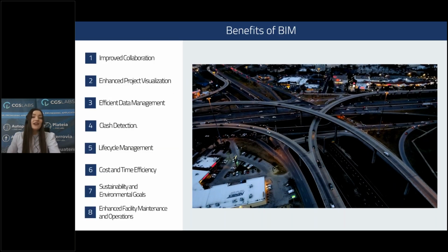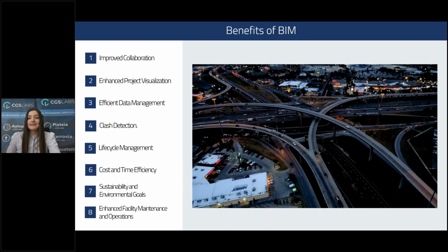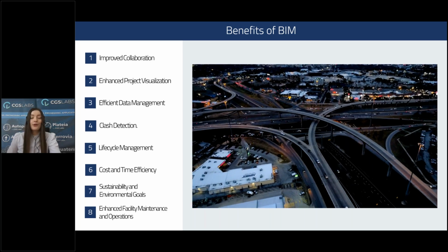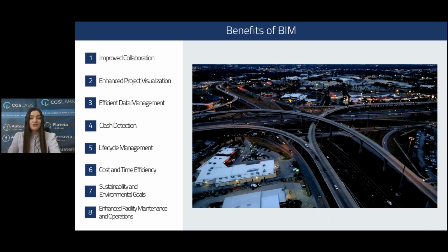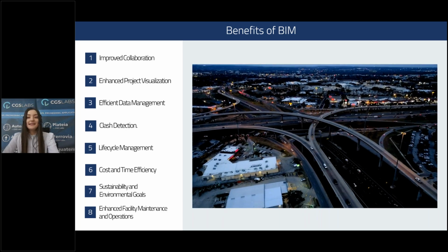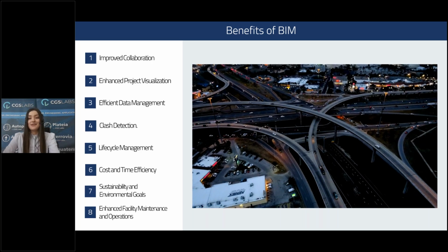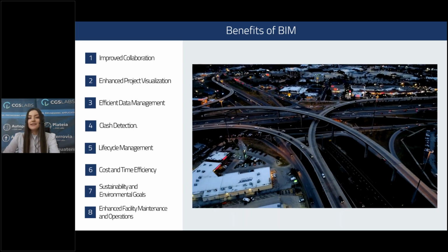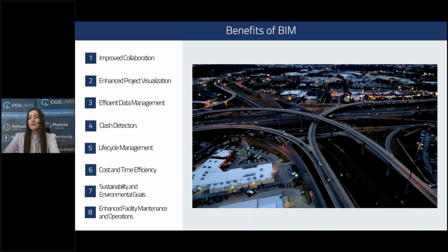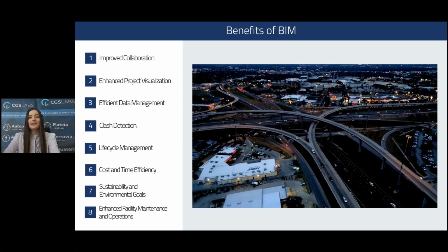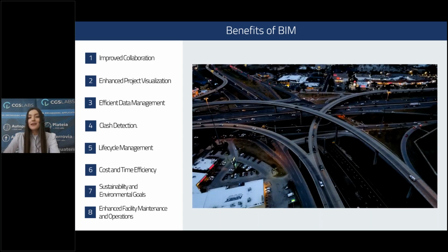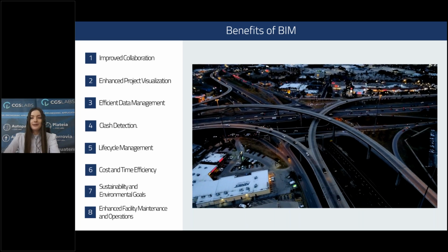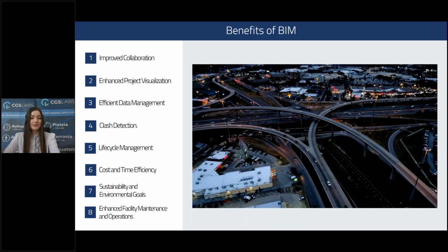The benefit of such collaboration is seen in saving time and resources throughout the entire life cycle of the object. So many issues that were once only discovered at the construction site can now be identified at the beginning of the planning process. This can be done using different tools to detect clashes, and submodels showing each construction phase are also very helpful. By adding a time component, we get what's called a 4D BIM model, allowing the animation of the construction process and simplifying the path to the expected results.